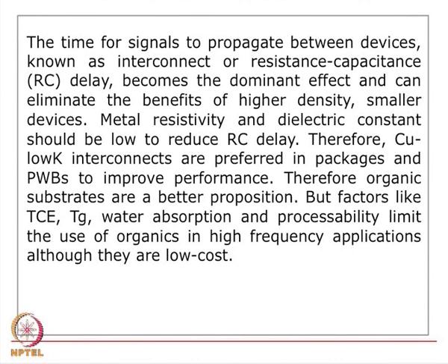Now, there is also another methodology where you are going to protect the die and the interconnects. Remember, this is a bare silicon die and you have the first level interconnects. At the back of the mind, you must always think about packaging as a means of protecting the die and protecting the first level interconnect, and having the package in a format that is now available for the second level interconnect on the printed wiring board. I think this big picture should always be there during this discussion.